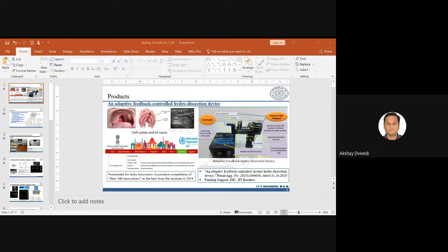And while this process is working, I give rotation to this tool so that these abrasives abrade the work material. And while they are doing this, they are also providing certain agitation in the electrolyte. And if that is happening, basically my electrolyte is getting replenished. In fact, I am getting fresh electrolyte into that zone.